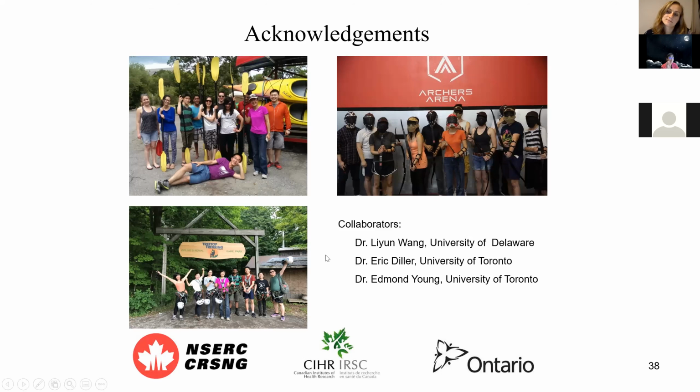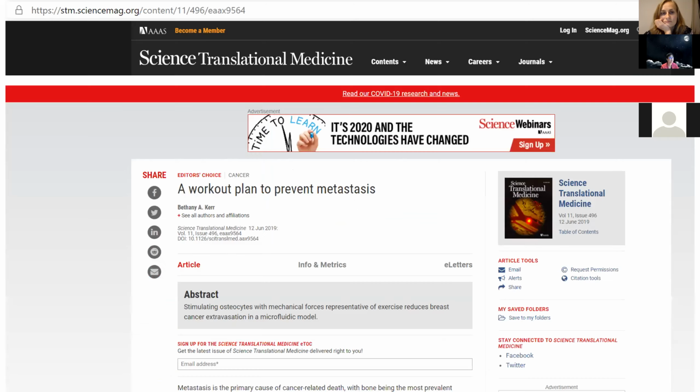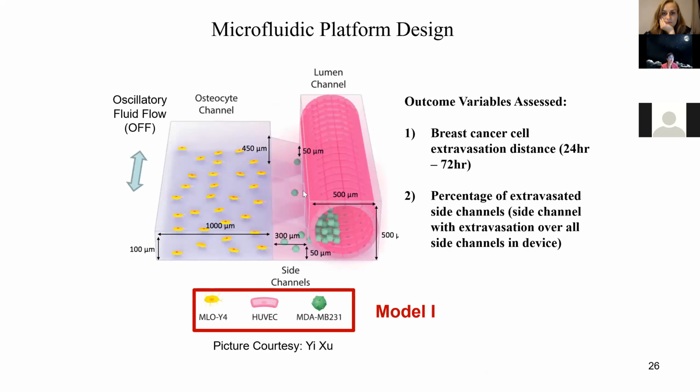Even though I covered it within one or two slides, fabrication of the device is actually very tricky. First, when you have the hydrogel-fused side channels, it's very easy for bubbles to get trapped.